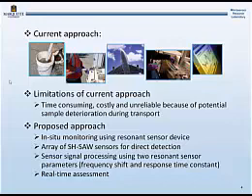So our approach is to use in-situ monitoring with a resonance sensor device, and our device is a shear horizontal surface acoustic wave sensor, and ultimately we want to use an array of these. And our sensor is for direct detection of the analytes in the liquid phase as opposed to headspace detection.